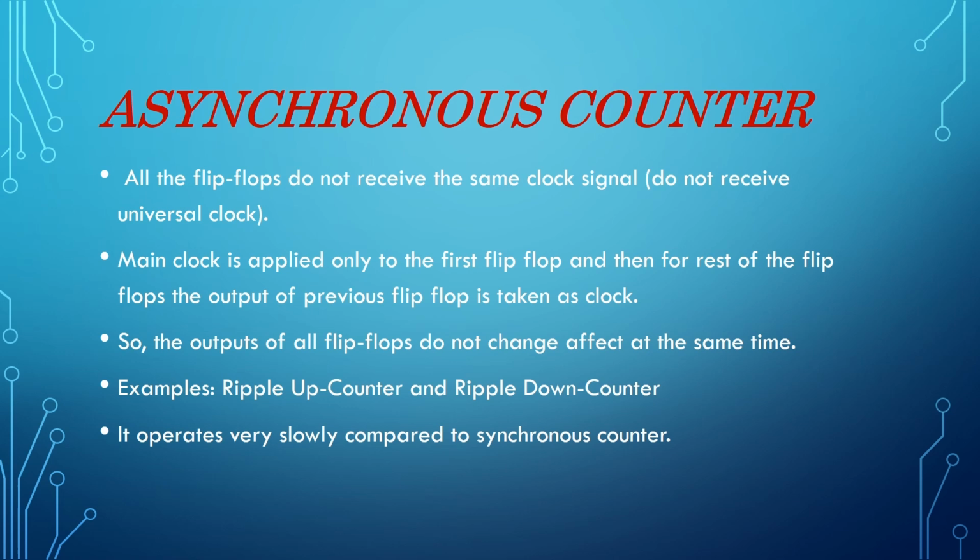So this is the asynchronous counter. All the flip-flops do not receive the same clock signal. As I mentioned before, the flip-flops do not receive the same clock signals. Why am I using flip-flops here? Because counters are made up of flip-flops. I will show an example of an asynchronous counter in the next slide.